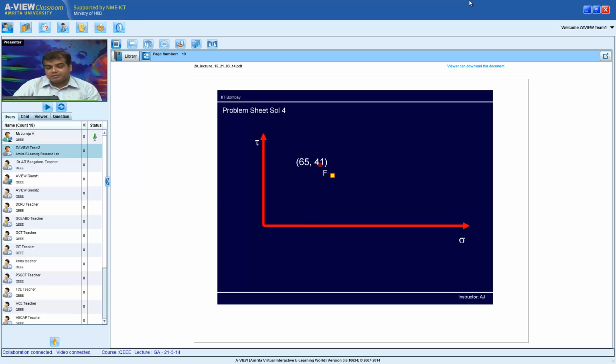These measurements were taken on the failure plane. Remember, in a direct shear test the failure plane is horizontal. So these values should be on my failure envelope as well. With this coordinate, and given that the intrinsic cohesion is 0, I can join the 0 value to this coordinate to draw the failure envelope.